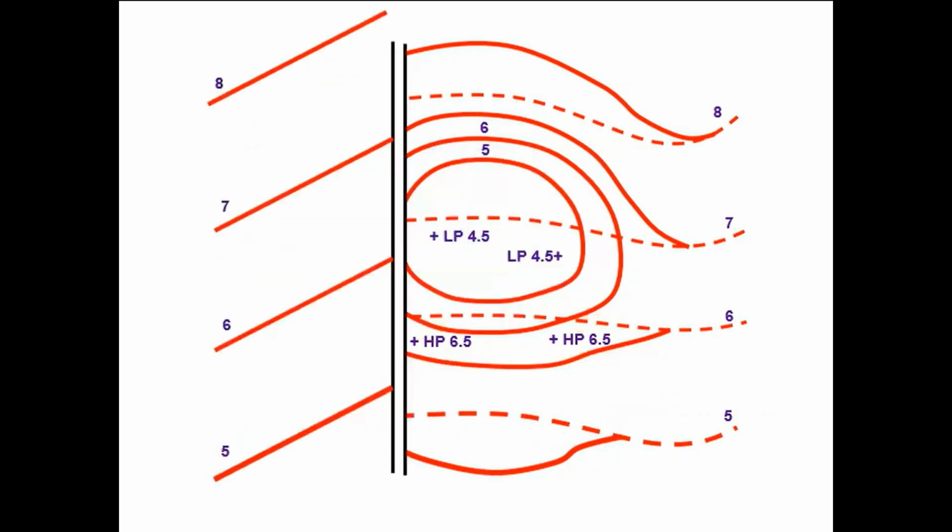Now we've added a parking lot, and that parking lot is just right up against the bioretention system. We basically have water flowing towards the curb. And the thing that students often have difficulty understanding is what happens to these contours that are on the back side of the curb. That is in this area over here on the back side of the curb. So to start with, let's talk about what happens to the ones as they come out from the parking lot. So this number 5, for example, it's going to come down, it's going to come across. It may well then run on the back of that curb and then over.